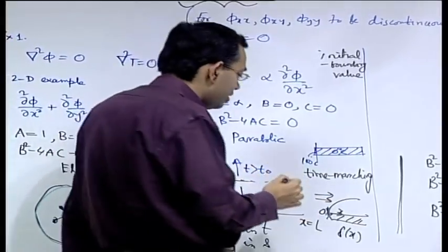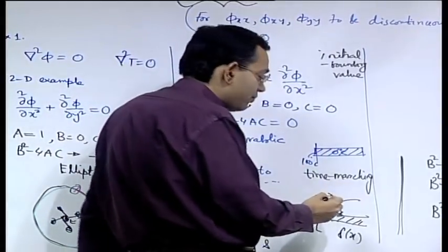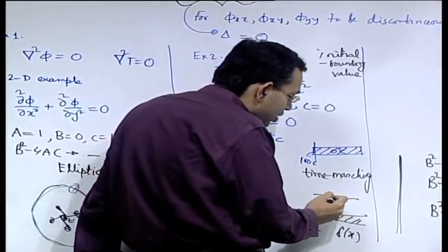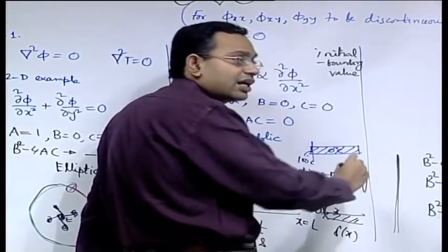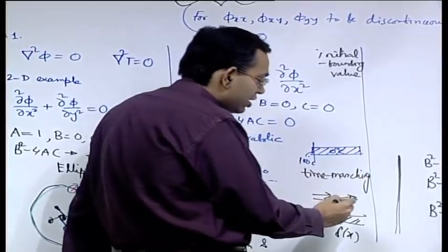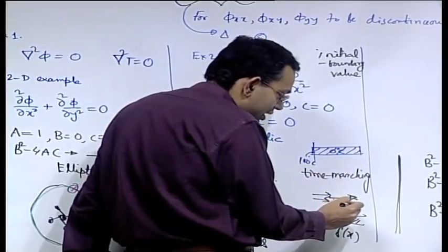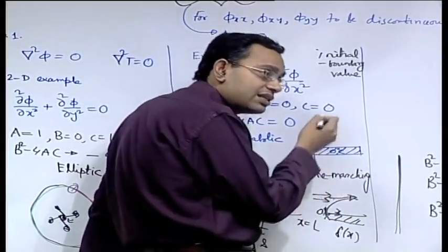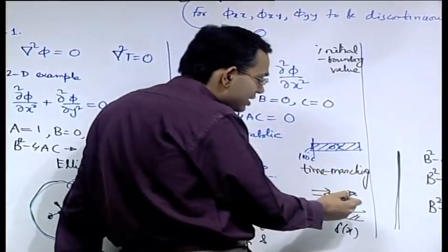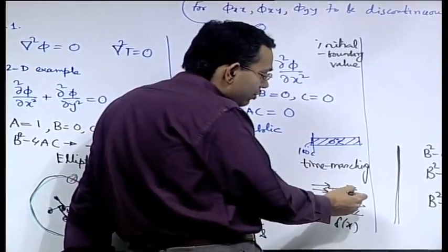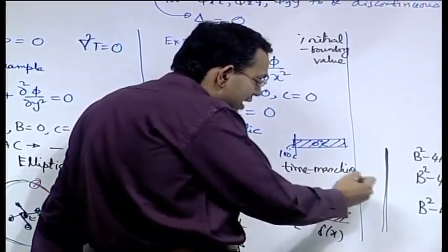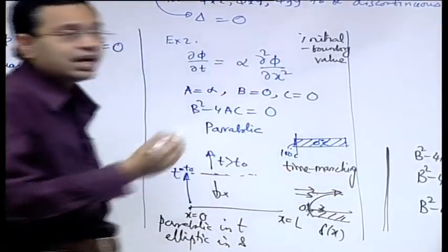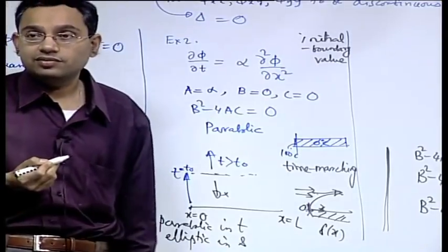So, because these are high Reynolds number flows, there will be a predominant direction of propagation of disturbance in the forward x direction along which it will march. There is definitely some viscous effect, but viscous effect will not be propagating this entire flow towards the other direction until and unless there is boundary layer separation.